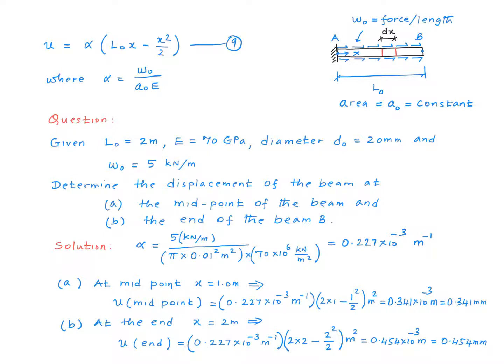To wrap this up, in problems like these, there are two key things to keep in mind. One, when we have a variable strain, we need to perform integration in order to get to the displacement from the strain. Two, we need to use suitable boundary conditions to evaluate the integration constants. Different problems will have different boundary conditions, and we ought to look for suitable ones to use in evaluating the integration constants.